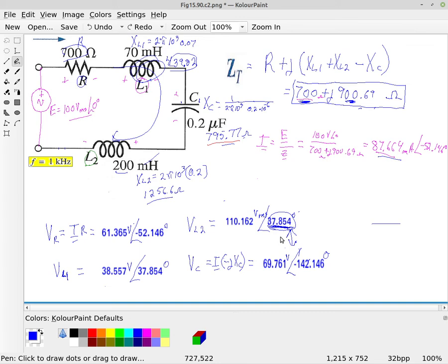So the voltage drop across any resistance, or the combination of all the resistances, will never be larger than the source voltage. But your inductors and your capacitors actually have stored energy within them, and so that's why they may have a larger average voltage drop than the supply voltage, because they've charged up, and then they're passing that charge back and forth between the inductor and the capacitor.